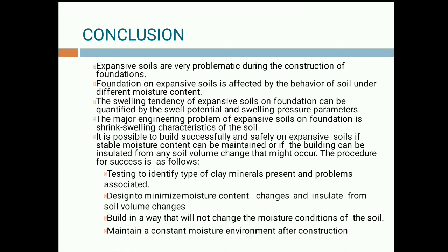The major engineering problem of expansive soil on foundations is the shrink-swell characteristics of the soil. It is possible to build successfully and safely on expansive soil if the stable moisture content can be maintained, or if the building can be insulated from any soil volume change that might occur.